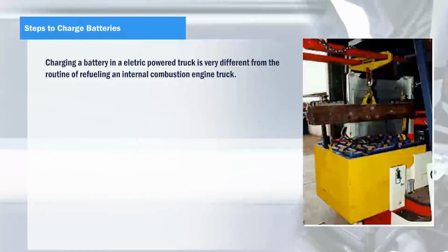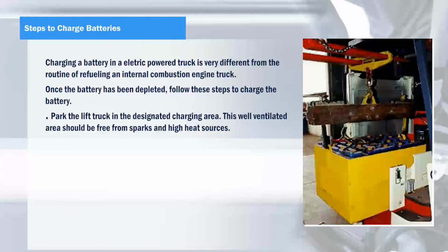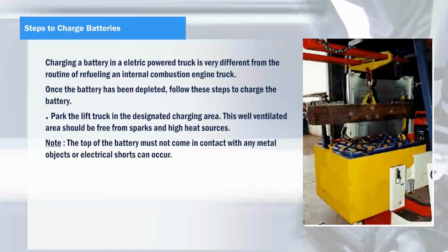Steps to charge batteries. Charging a battery in an electric powered truck is very different from the routine of refueling an internal combustion engine truck. Once the battery has been depleted, follow these steps to charge the battery. Park the lift truck in the designated charging area. This well-ventilated area should be free from sparks and high heat sources. Note: the top of the battery must not come in contact with any metal objects or electrical shorts can occur.